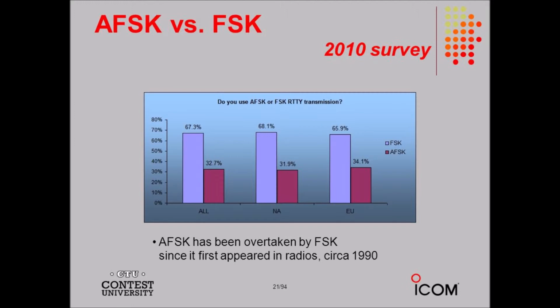In an AM signal, the bandwidth equals twice the highest audio modulating frequency. Page 435. In the example of figure 25.3, all the AF voice energy exists at or below 3 kHz, so the signal bandwidth equals 6 kHz, typical of AM voice communications.